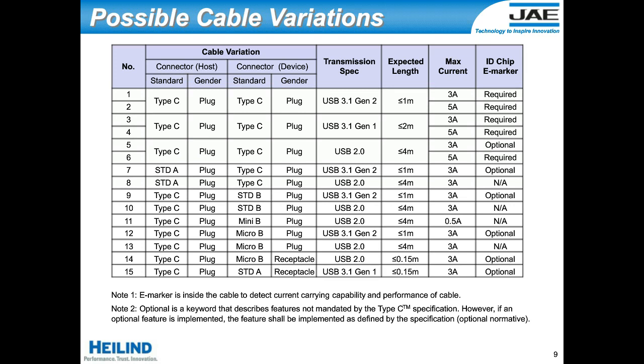The cables which have legacy connectors on one end or only support slower speeds have much fewer pins that are actually terminated. Obviously, if you remember the old original USB Type-A style connectors, they only have 4 pins, and even the versions that support the higher USB 3.0 or 3.1 data rate only have 9 pins.